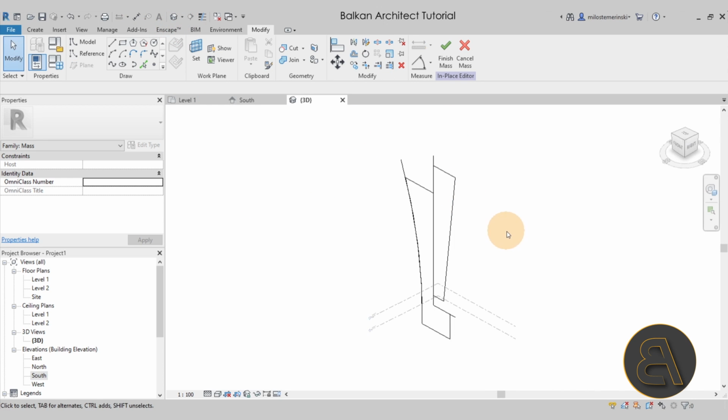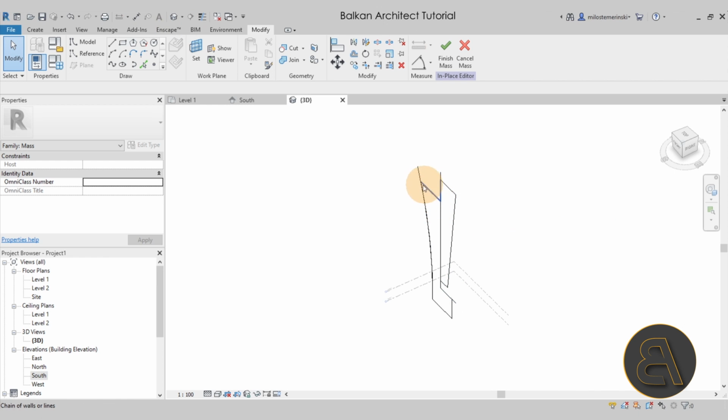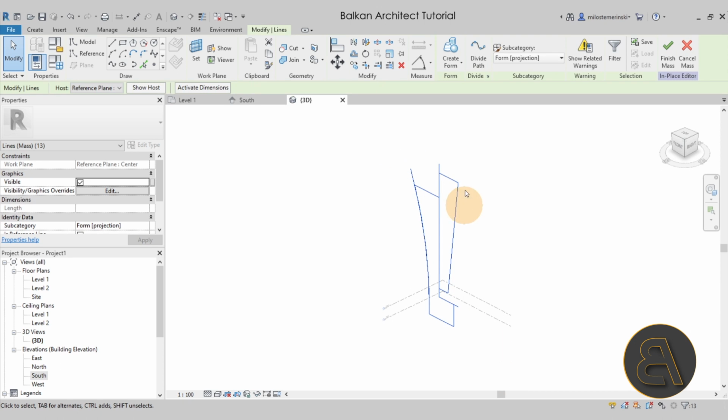Now, if I go to the 3D view here, as you can see, it looks like this now. So we have the shape, and then we also have these 2 lines. Revit doesn't really know what we want to do at this point. So in order to create our main building shape, you want to select everything. Then you hold the shift key, and notice how next to our cursor we get that little minus sign. Now we can remove this line, and then this line from the selection. So now we just have a continuous chain of lines that create the shape of our building.